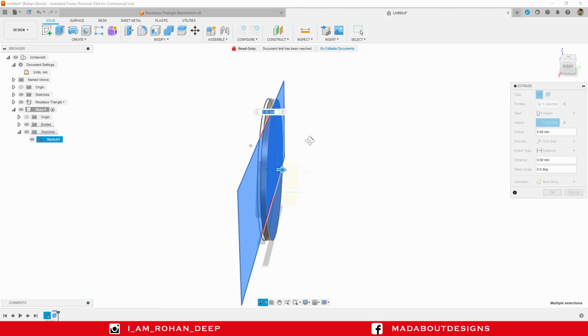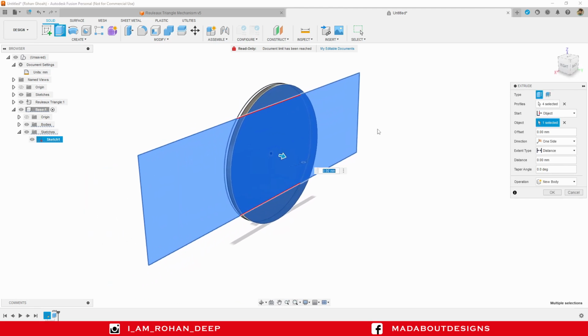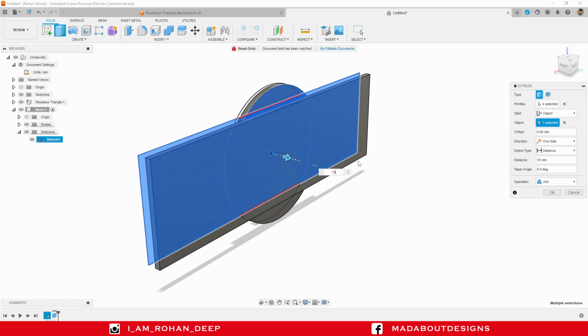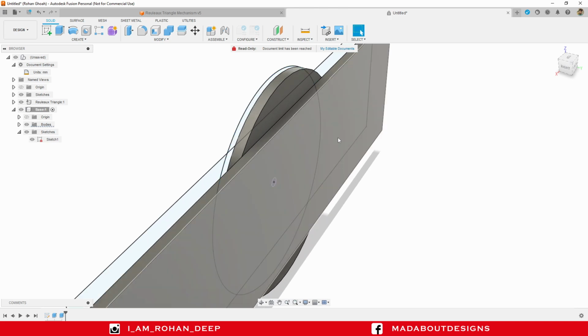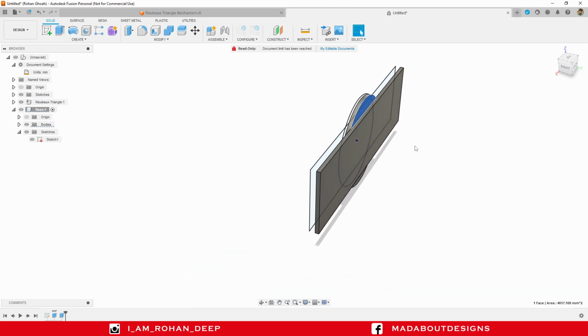So the sketch will be extruded from this surface. Extrude it up to 10 mm. Operation Join, click OK. Here you can see the rectangular profile has been extruded from this surface rather than this profile.